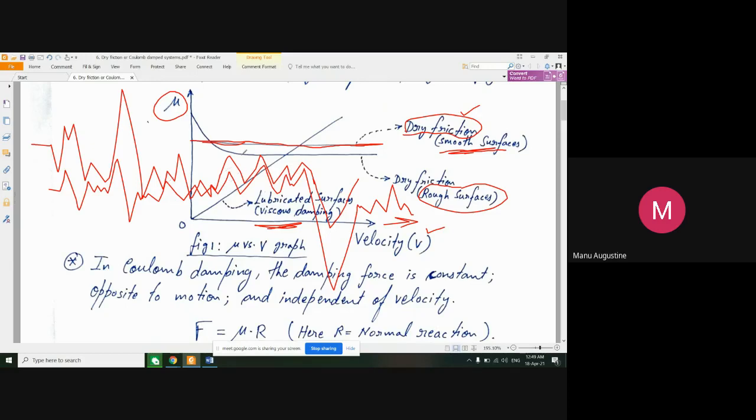So in such a case, you see, an interlocking of surface peaks and valleys occurs. What you need to understand is that when you try to move surfaces with such heavy interlocking relative to each other, the resistance to motion will be very large initially. But as soon as the surfaces start moving with a certain velocity, then with the increase of velocity, these hills and valleys won't get time to come down and settle over each other.